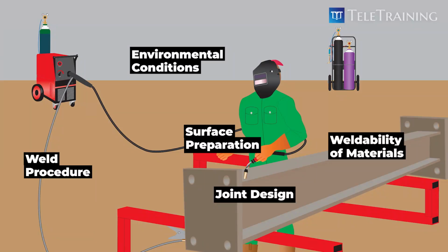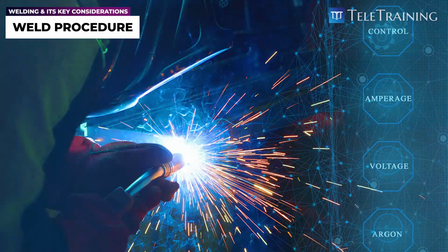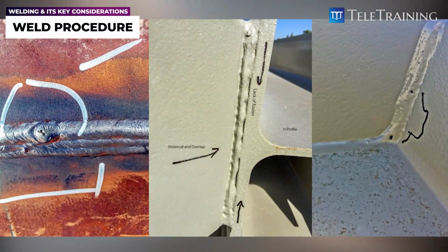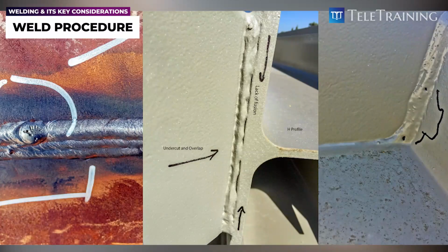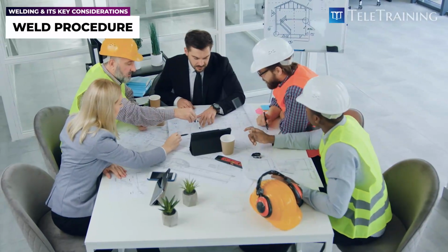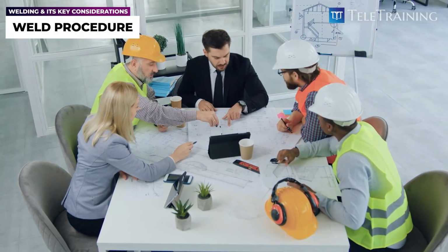Let's look at the last factor, weld procedure. It is crucial to have a comprehensive weld procedure that defines the basic weld settings, like arc voltage, amperage, and the weld gun's travel speed. In fact, incorrect weld procedures and incompetent welders are the main causes of weld defects. That is why it is crucial for extensive planning of welding work, ensuring all necessary qualifications, weld procedures, and weld maps are in place prior.